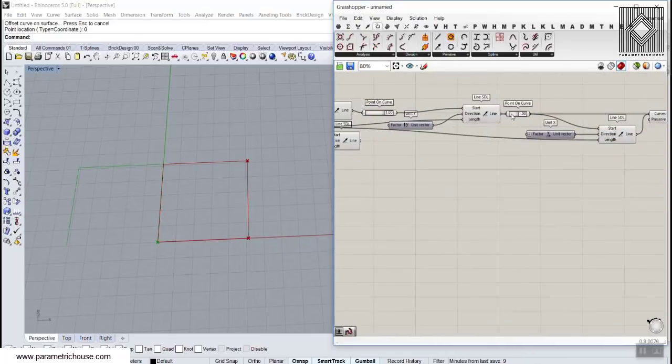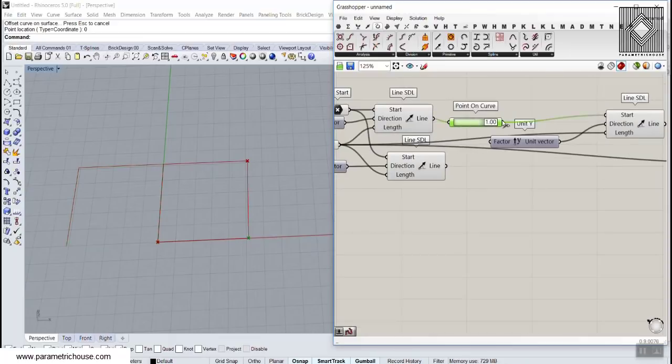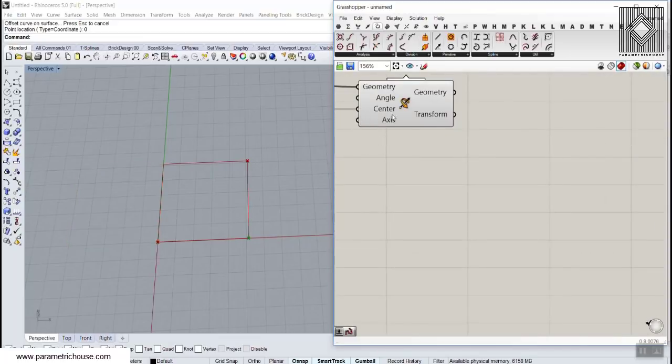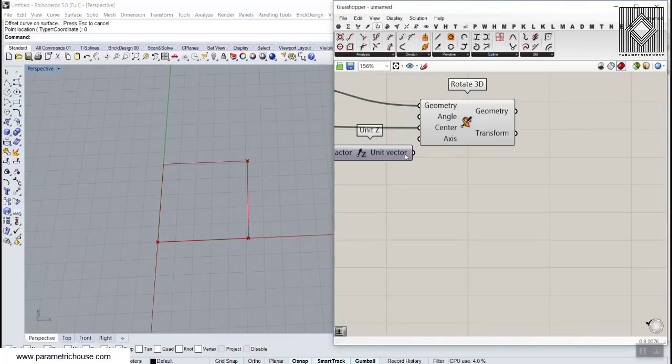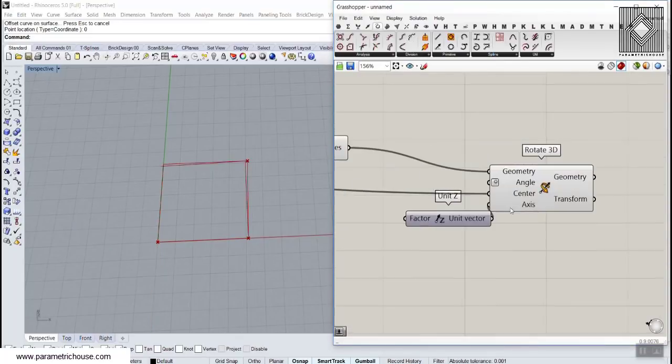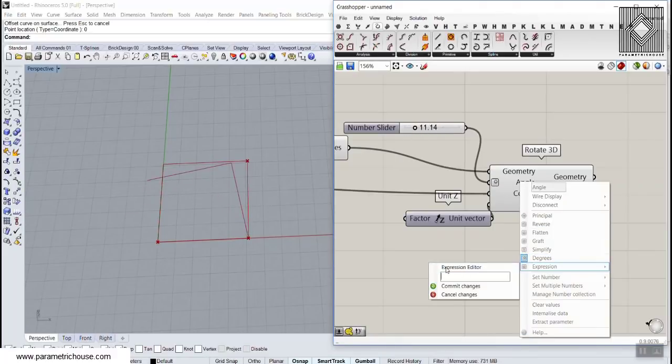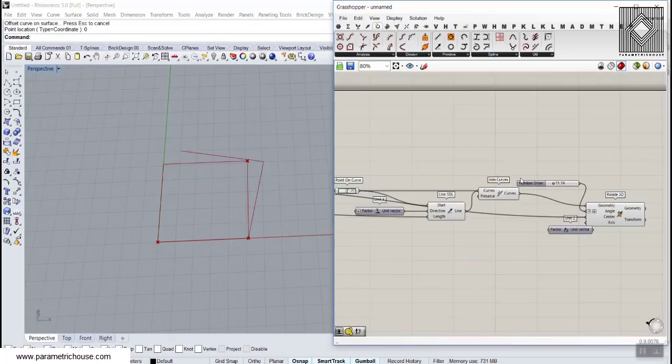The center of rotation is somehow starting from here, and the axis is Z direction. And here we go, we can give this a degrees. I've explained that because we can't use degrees here, we have radians, but I just converted that to the degrees. Okay, so maybe we have 0 to 60 degrees. I don't really know that. Let's just see. Okay, it's rotating inwards, so we can give this a minus X to make it outwards. Okay, and we turn this off, and here we go.